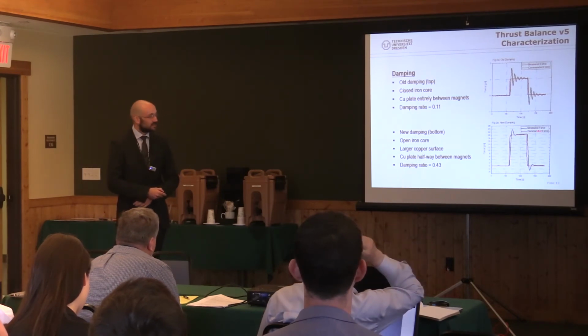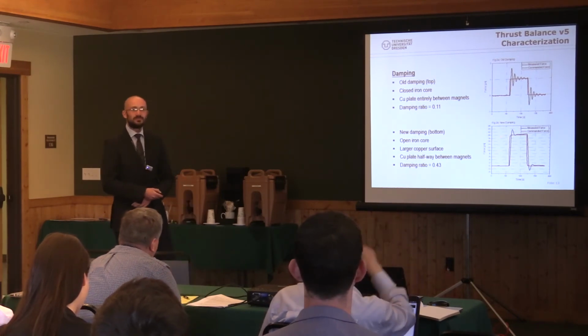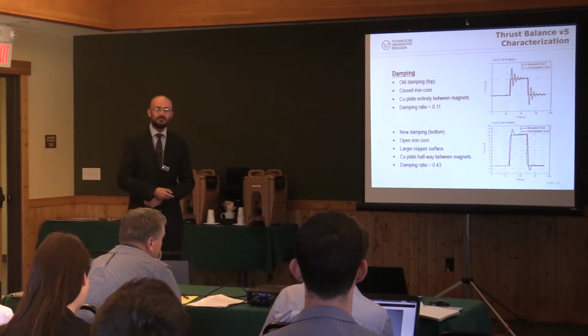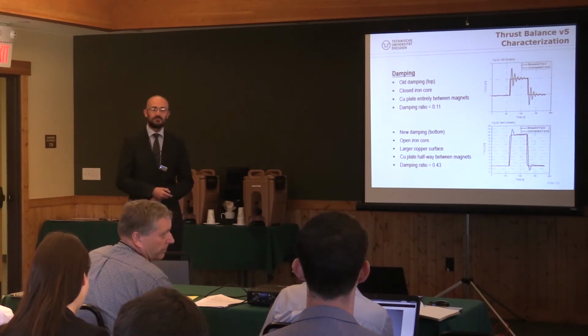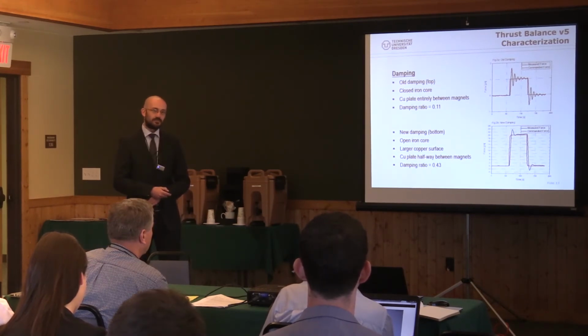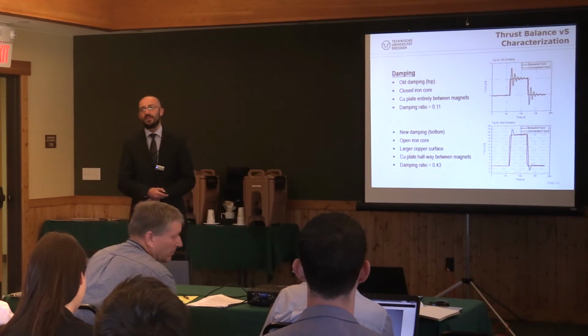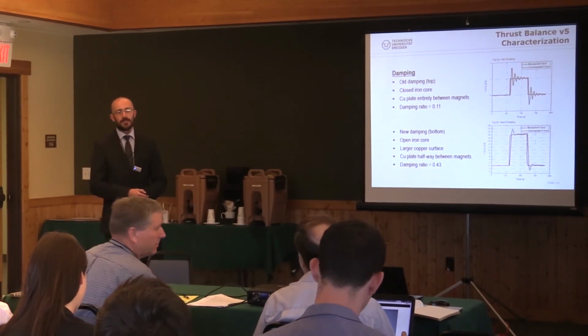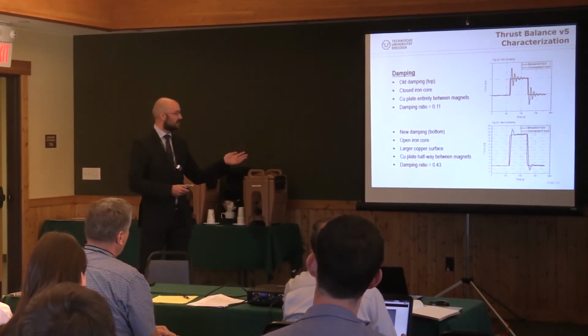You know that JPL, Caltech had a very thorough report last year with recommendations for micro thrusters in the torsional panel. And actually they recommend to have a damping ratio of around 0.5, 0.4 like you have, and not 1. Yeah. That paper also said that 0.8 was fine as well. Yeah, I've heard that same paper. Yeah, like I said, I try to aim for 0.7.